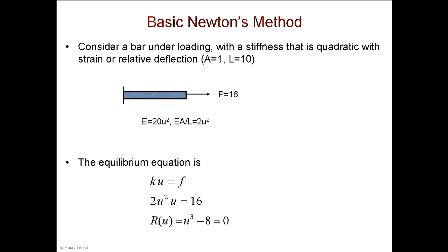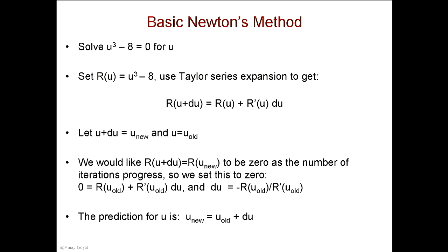To do that, we're going to use our favorite thing in the whole universe, the Taylor series expansion. I'll show you how to do that. And again, I can't tell Abaqus, hey, I have this huge nonlinear system of equations, can you solve it exactly for me? It won't do that for you. We need to find a systematic approach, because that's the whole point of solving these nonlinear equations. So in this case, what you can do is use Taylor series expansion.